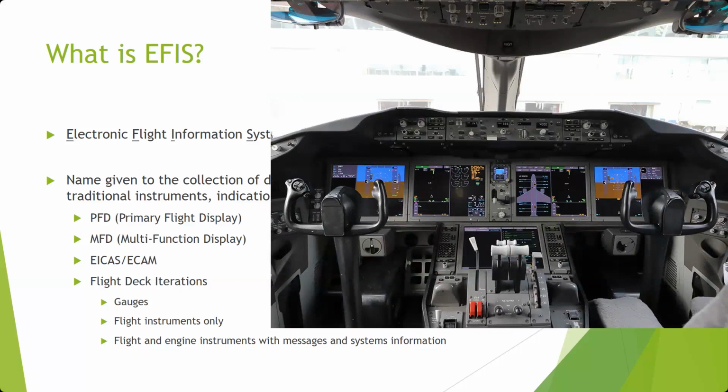The electronics are pretty robust, but even here, 787 still has, now it's got a digital backup display in the middle. It's called an integrated standby instrument, where it has a horizon, speed, altitude, and direction. But this one instrument, not only is it like this, but it's got a battery attached to it. So it can run all by itself, even with a full electrical system failure.